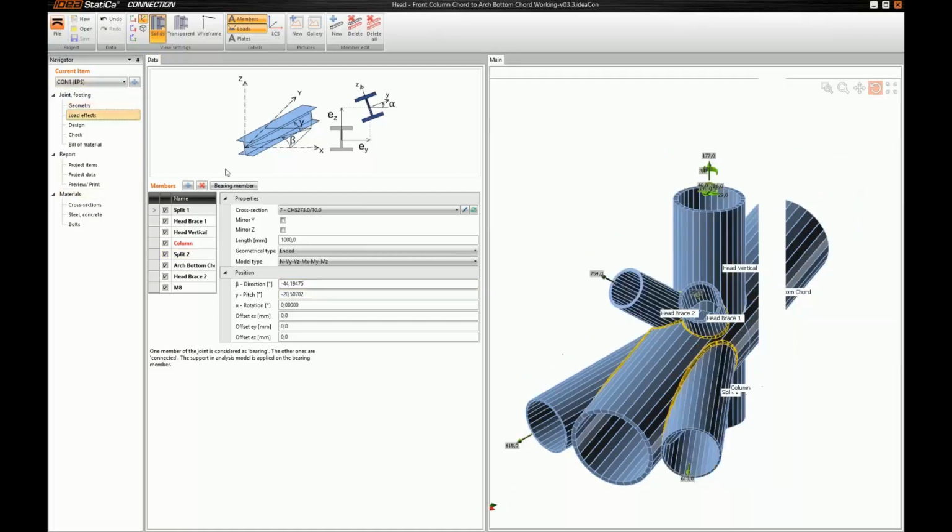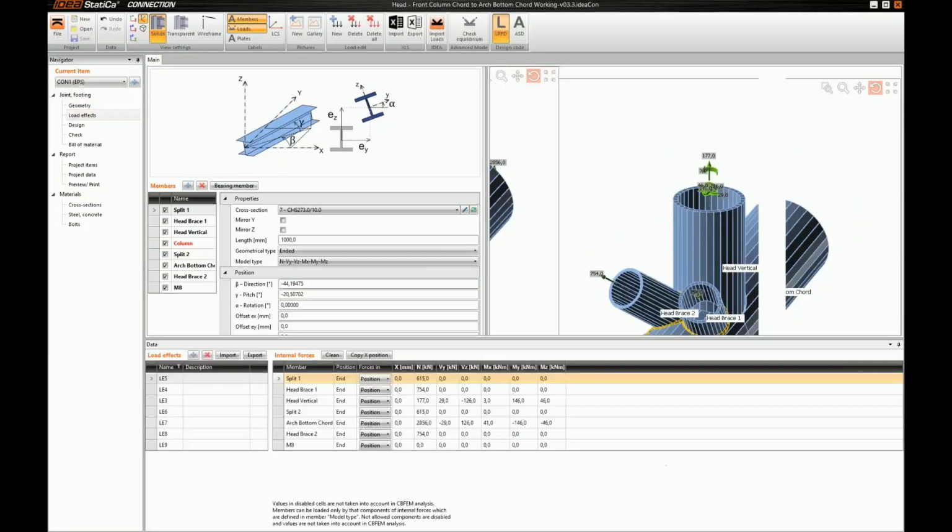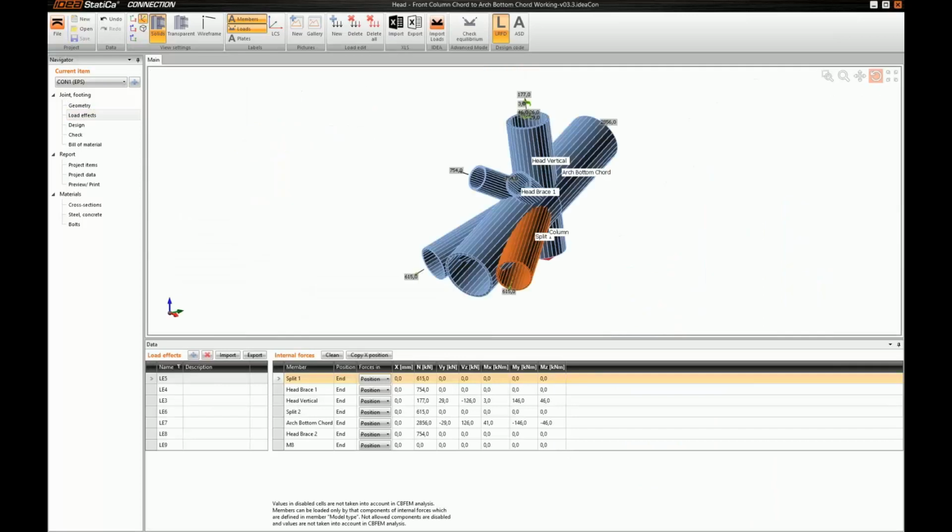And second is that we have automatically inputted the loads on each member for 8 load cases that come straight from Autodesk Robot. Since the results come straight from a global analysis model, they respect equilibrium and make sure that the exact stress calculated in our global analysis is correctly replicated in IDEA StatiCa.